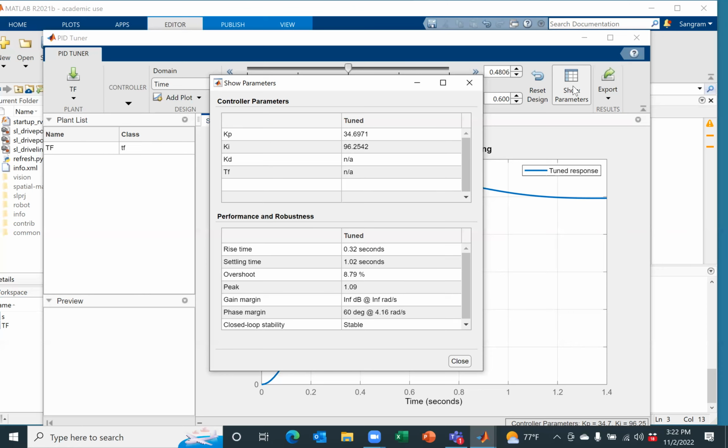When we linearize a non-linear function, we are taking a very small part of a non-linear equation, right? So will there be an infinite number of PIDs? No, basically what they do is you look at the nonlinear behavior of the system.